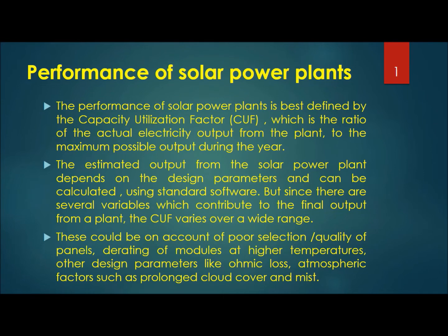Now the performance of solar power plant. It is a very important part of any solar photovoltaic system. The performance of a solar photovoltaic plant is best defined by the capacity utilization factor, which is the ratio of actual electricity output from the plant to the maximum possible output during the year. The estimated output from the solar power plant depends on the design parameters and can be calculated using standard software, but